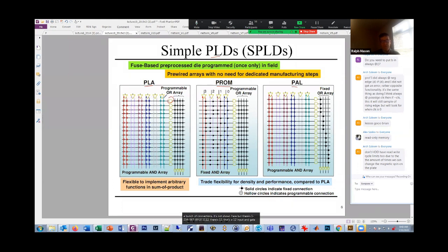And I've just put them on one line. And this circle says there's 1, 2, 3, 4, 5, 6 inputs. And then we have the signal and its complement coming out. And these little bubbles say these are our little places where we can program. They can either be opened or closed, whether we program them. So we can make any logic function of the 6 inputs, any ANDing of the 6 inputs or their complements into this one gate. And likewise, there were many of them.